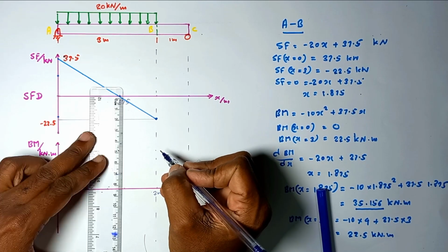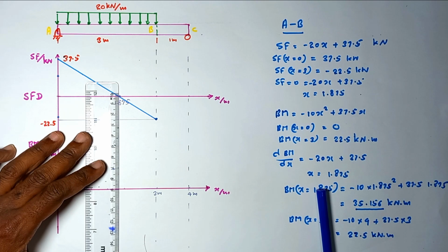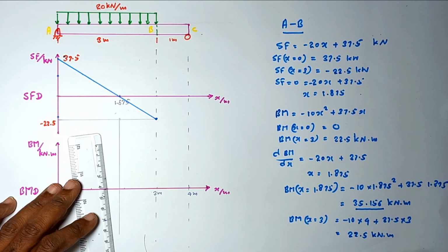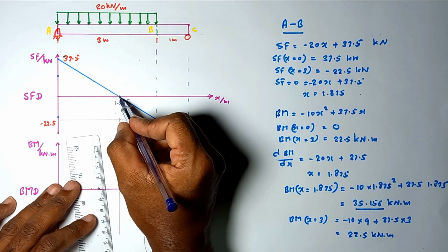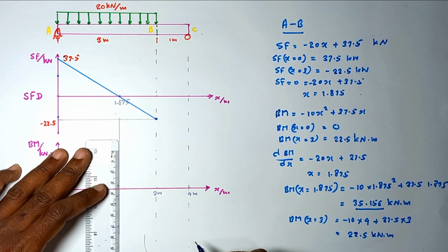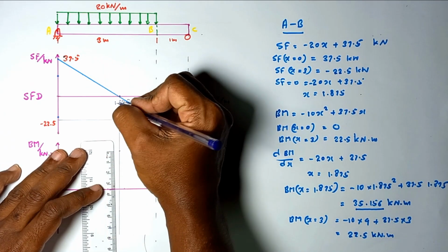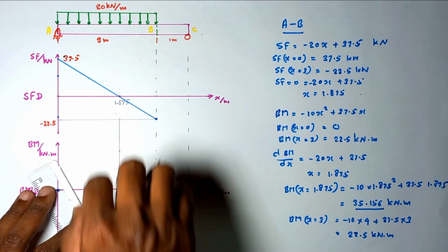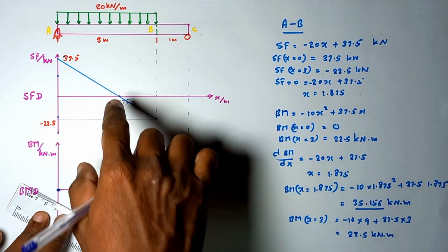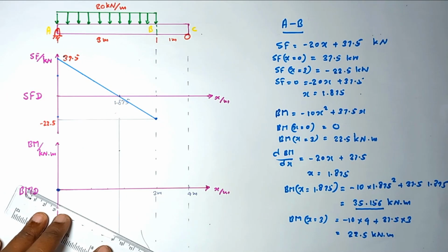You all know as the shear force curve, we are getting the derivative of bending moment curve, so that at this point the bending moment should be maximized. So the maximum point we are marking just below this intersection point of the shear force curve, because at the maximum its derivative is equal to 0, so that the shear force goes to 0 at this point.